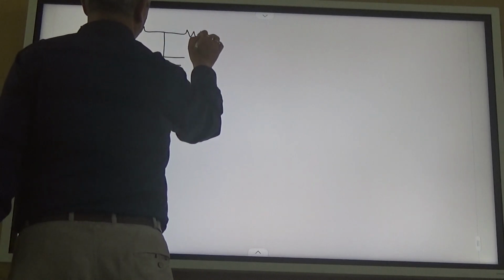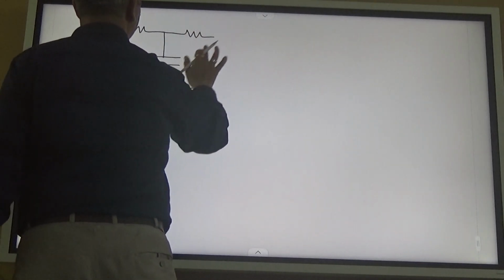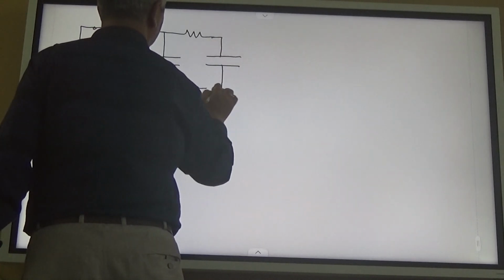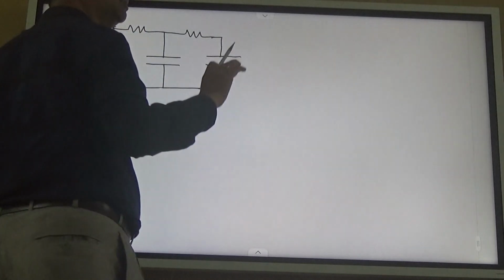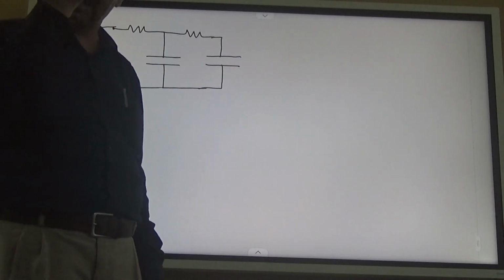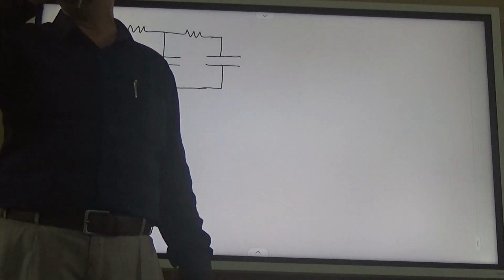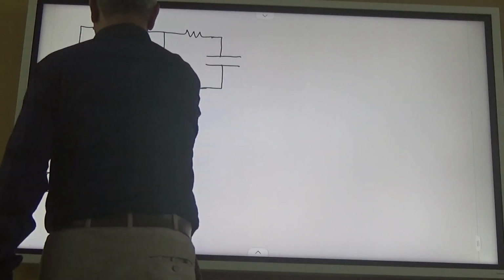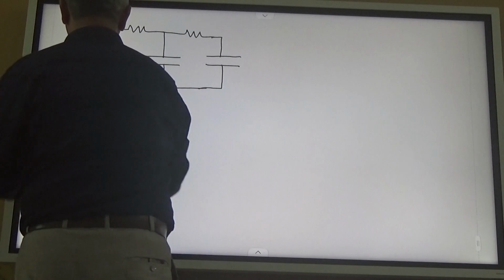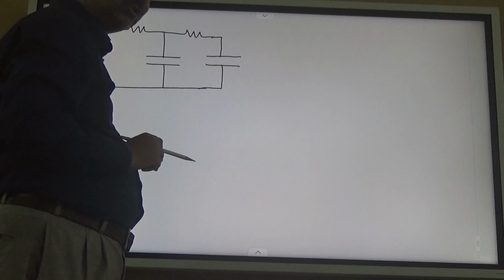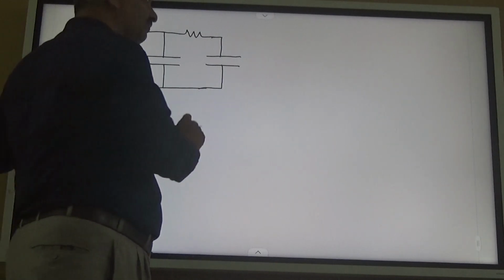So Kirchhoff's laws, you have studied that at any node, the algebraic sum of currents equal to 0, that is the classical definition, but what is the working definition? At any node, currents incoming equal currents outgoing, we assume one direction, and if the answer becomes negative, it is actually the reverse direction, right? Okay. So this is now a common terminal, ground. We say this is 1 volt. Common means with respect to this, we measure all the voltages. This is a common terminal. We also call it ground. With respect to this, we measure all voltages.